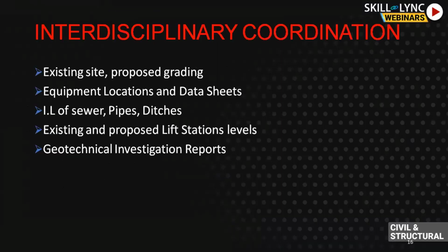The most important thing is interdisciplinary coordination. This is not like bookish design work in university. When you proceed with any civil structural design, what do you need? First of all, for any clarifier design, you will need the grading levels of that site, because before this you cannot proceed. This will tell you whether the soil is in cut or in fill, how much overburden will come on your foundation, and what loading you will consider when you take soil load.